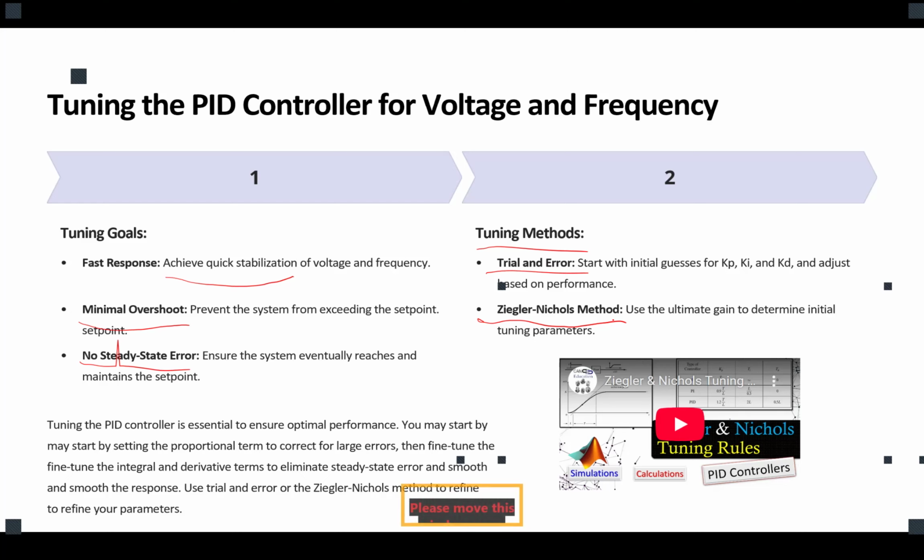That being said, the Ziegler-Nichols method has a very significant advantage, and it's in initial tuning. In manual tuning, you don't have an initial value for KD, KP, KI. You just put in a number randomly. Ziegler-Nichols tries to create an optimized value for the initial value and then adjust it with the autotune. Are we good? So this is one of the most significant applications of Ziegler-Nichols, the initial value of KP, KI, and KD. Are we good?